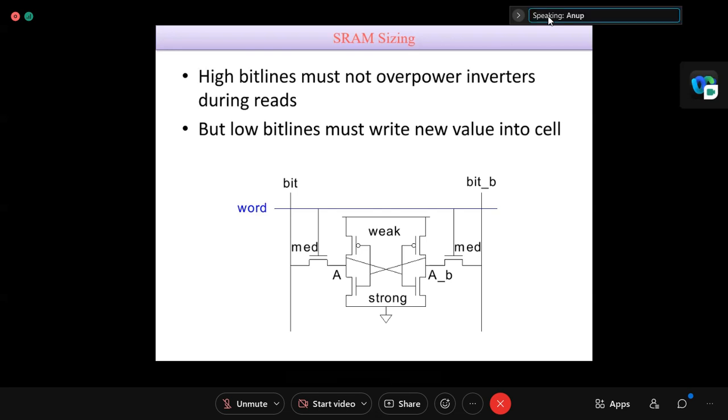And if we are doing digital logic, normally we keep the L constant, because normally for MOSes we use, let's say, 65 nanometer. What does it mean? The channel length, the length of the MOS, is 65 nanometer, and the width is supposed to be more than the length. So it is supposed to be 2 times L minimum.